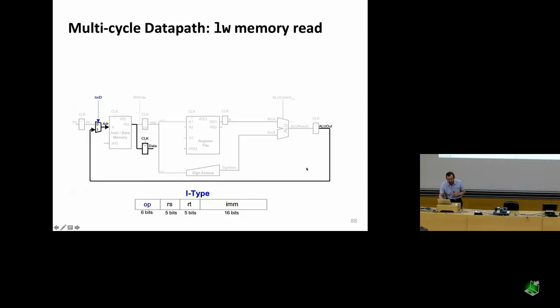And in this cycle of processing, the 4th cycle of processing of the load instruction, we should take the address to feed into instruction data memory from this input of the mux. So now your control signals are dependent on which state you are in. That's exactly what I said a few slides ago, right? Now you can read the instruction/data memory with the address that is produced by the load instruction, and you get the data and you latch it again.